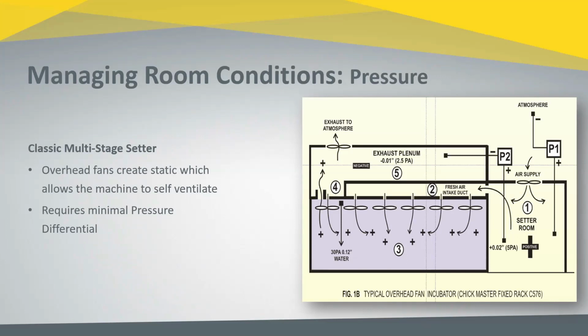And reference 3 or point 3 is the positive side of the fan. And if we look at this, when these fans are operating, we recognize that there's as much as a 0.12 inches of water column static between the negative to the supply in these internal fans, with the internal fans operating.